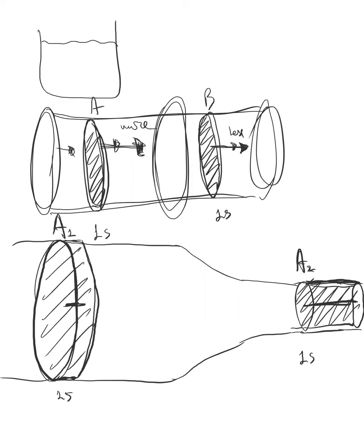And the length of the stream of water that goes through the section is almost by definition the velocity of this water, of this fluid. So my conclusion from here is that water must flow faster in section A2 compared to A1. So faster here and slower here. And this follows again from the fact that liquid cannot be compressed, and you have to have the same overall amount of liquid going through all sections at all times.